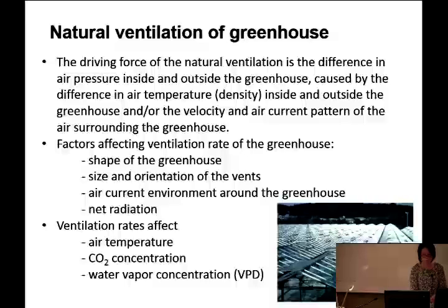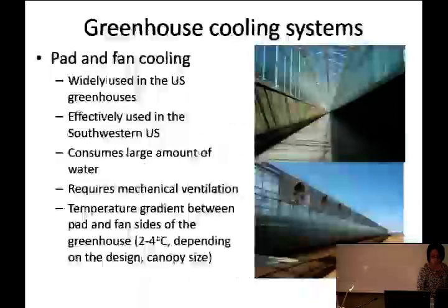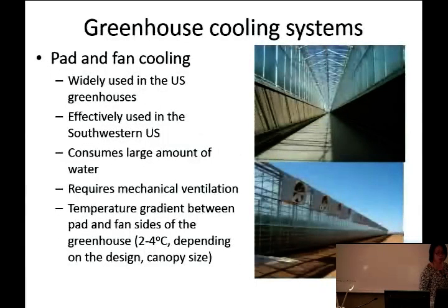And why ventilation rate is important: you see in several charts I have, or the drawings I have regarding energy and mass balance, every single one has ventilation as a key component to change the status. So it would affect air temperature, it would affect CO2 concentration, it would affect the water vapor concentration or humidity. Okay, so that's why understanding ventilation is very important.